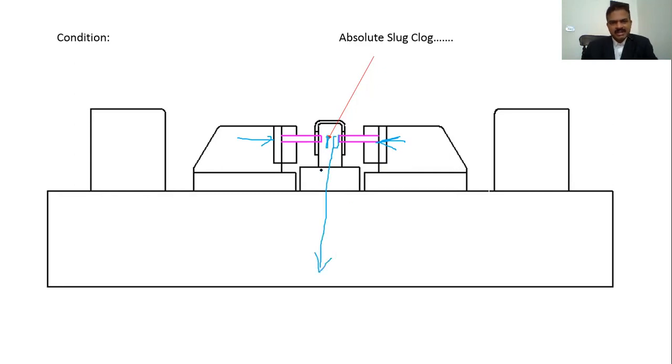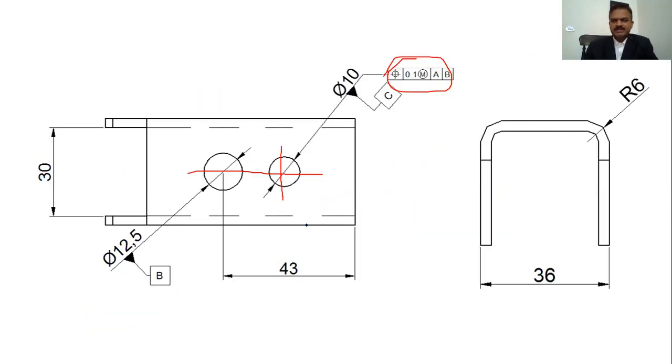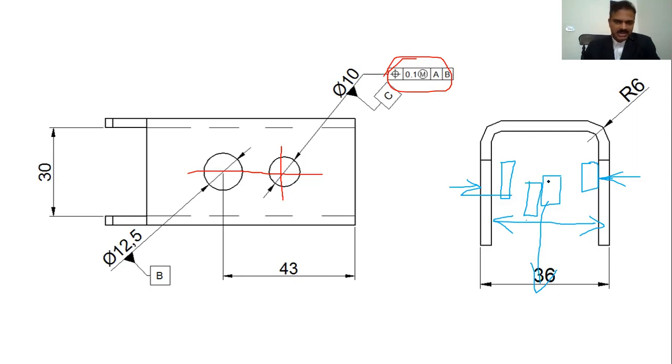But what is going to happen here is, this is basically just barely 30 millimeter width. So if you look at the basic numbers in the part, this gap here is barely 30 millimeter. So I'll just try to draw it here. The slug which is coming inside when it is cut, and the cam cuts this piece, this is going to pile up here because there is not much gap here. Definitely it's going to pile up because there are 2-3 millimeter thick slugs coming from both sides. Also, it will be drenched in coolant for better cutting.